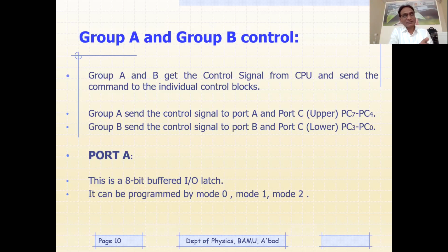And when the microprocessor is transferring data to the output device, you need a latch circuit, right? Latches hold the data for the time being, so that you will be able to visualize the data. Otherwise, the data bus will be holding data for less than 1 microsecond, which is not enough for the human eye to visualize the data. Therefore, you need to latch the data.